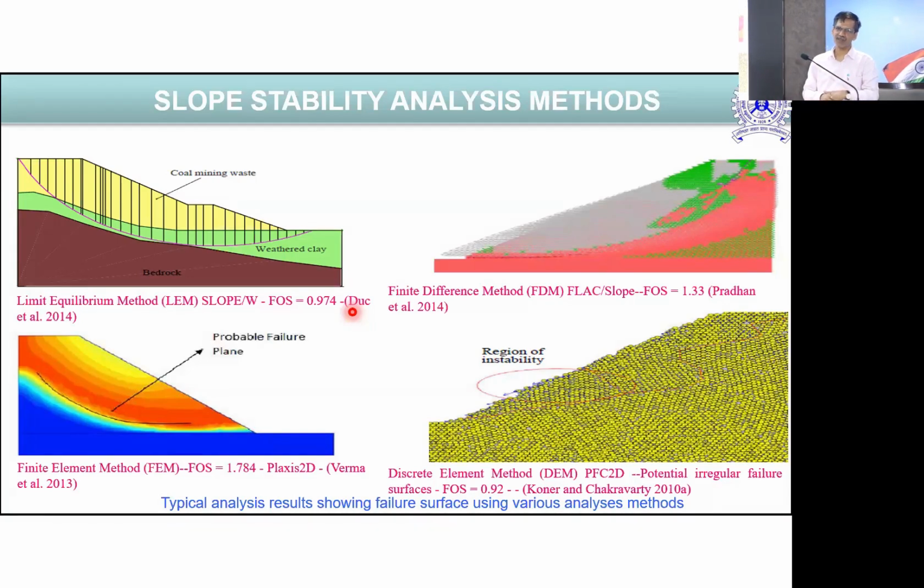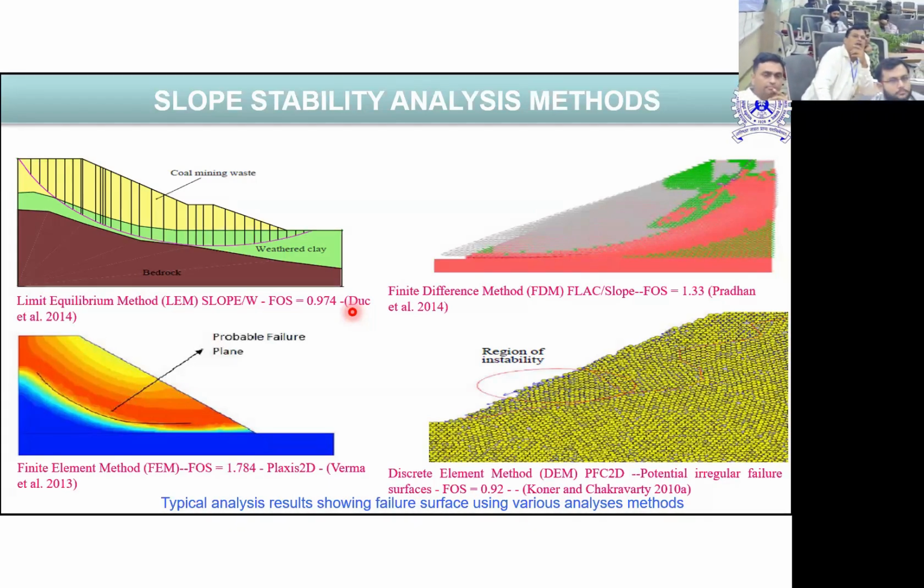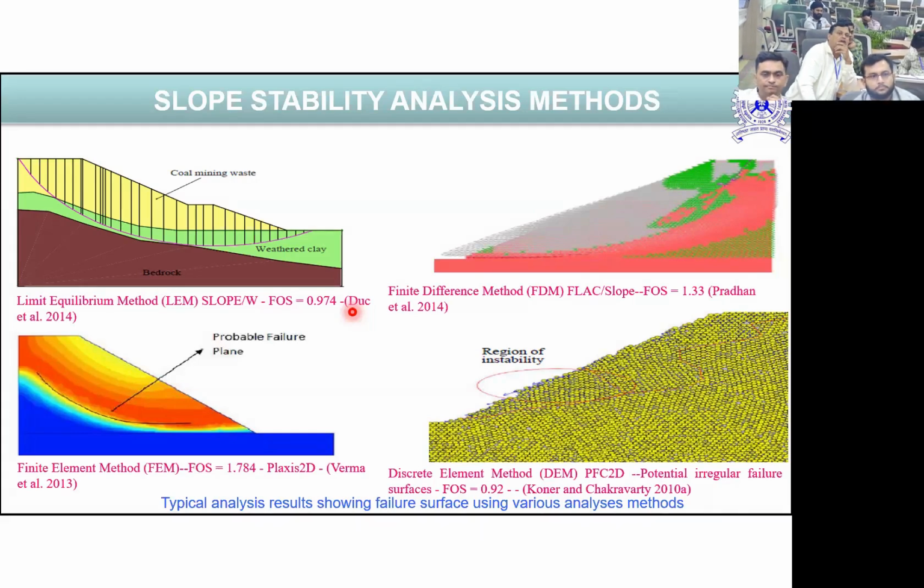And that will be an upstream failure. Sudden drawdown is an upstream failure, obviously, because it was pressurized at the beginning, and then that happens, so that means pore water pressure and so many other things are there. So that is what we need to check: what is my embankment, and is there natural soil in the embankment? Accordingly the critical situation will be different.